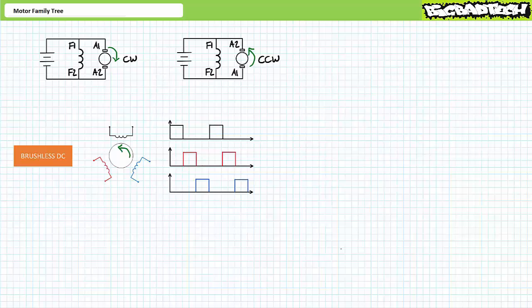Now that we've got an idea of how traditional DC motors operate, let's reintroduce the brushless DC motor. A brushless DC motor is essentially the opposite of a permanent magnet DC motor and features an electrically excited field winding and a permanent magnet armature. In a weird sort of way, wrapping back to one of our earlier motors we discussed, the brushless DC motor has far more in common with a permanent magnet synchronous motor than it does traditional DC motors. You can think of it as convergent evolution. It's still lumped into the DC motor family because it is intended to operate using fixed polarity DC. Like a permanent magnet synchronous motor, a brushless DC motor features a permanent magnet armature, thus freeing it from the necessity of brushes and a commutator.